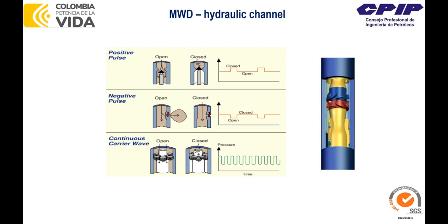As a geosteering engineer, you just have to make sure that all the data you require for your geosteering decisions is programmed in the tool, and that it has enough bit rate to be sent with proper data density, at least 2 points per foot. That can be done and verified at the pre-job stage.